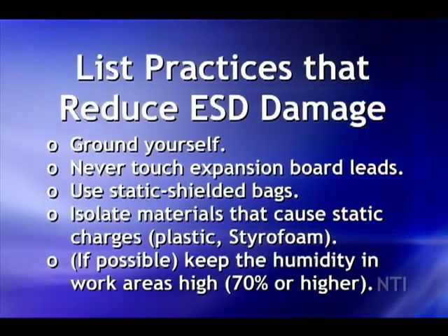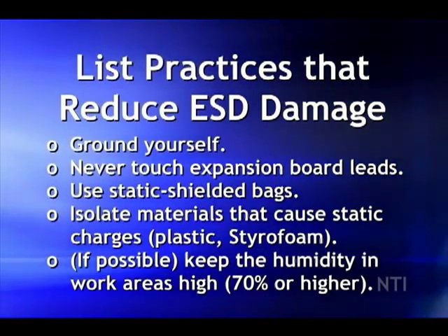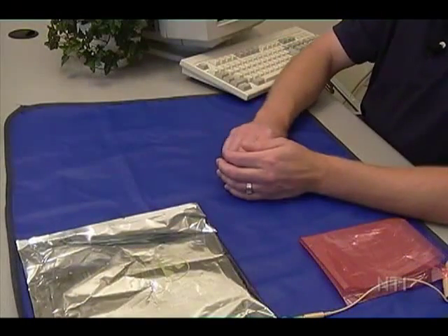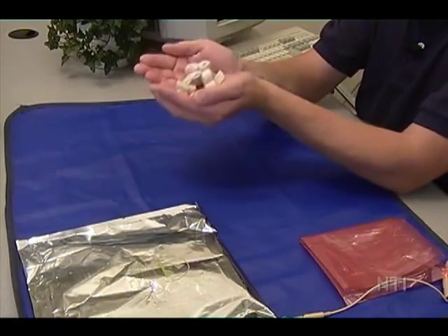Rule number 4, always keep sources of static away from computer components. Now, the two big culprits that I've experienced with this are styrofoam and plastic. I have a sample here of some packing peanuts. These can build up a massive static charge in you just by touching them.